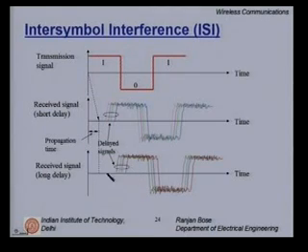Here, for the case of long delay, I still get the received signal delayed, and then each one of the components is delayed further. Here I have shown only 1, 2, 3, 4 clear reflections. There could be more. And then they can start interfering with your subsequent symbols, and hence the ISI.